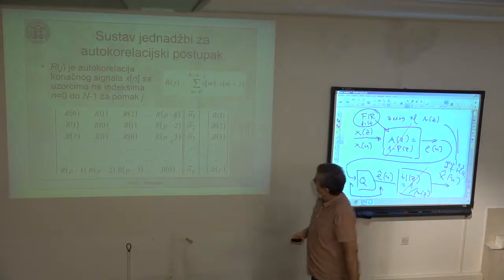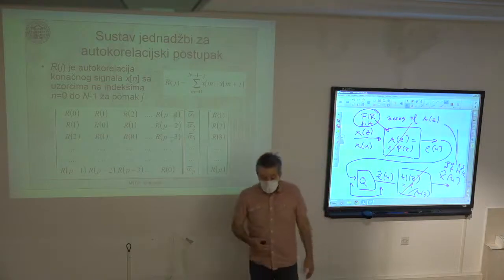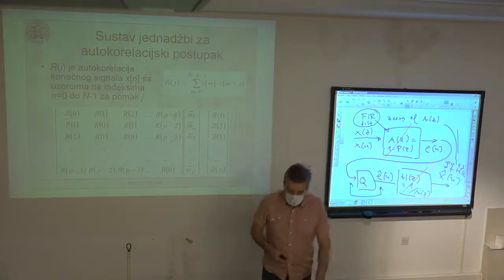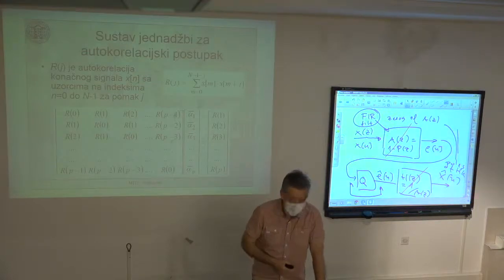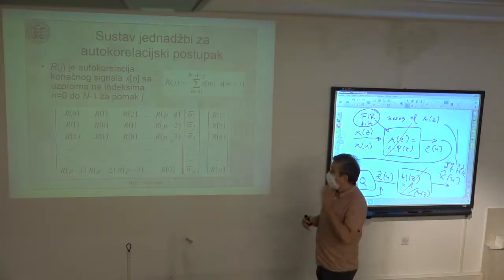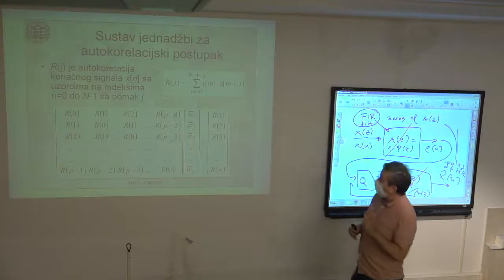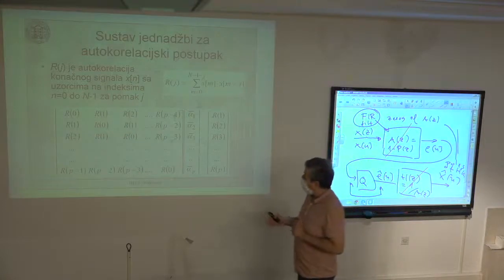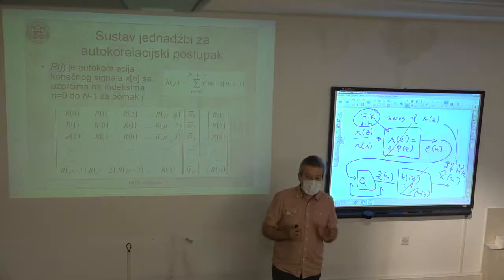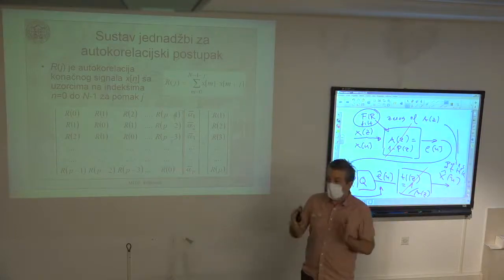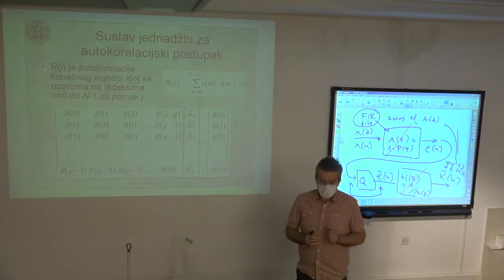Okay, and just as an example of the actual speech coding algorithm that you use every day on your mobile phone, once you are speaking on one side, this linear prediction coding of speech is performed by computing the optimal predictor, typically 50 times per second or up to 100 times per second.